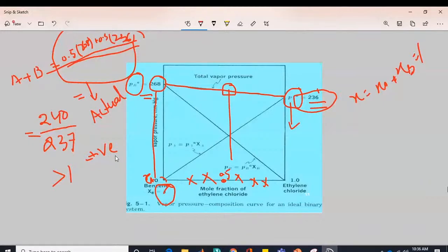Okay, the net result is an increase in the rate of mass transfer into vapor. Now this is another equation to understand how vacuum distillation works. Actually, it is the mass of the vapor formed, you can say. The equation is the vapor pressure of the evaporating liquid divided by the external pressure. Now remember, we are talking about the mass of that component, how much can be achieved. We have two factors. One is the vapor pressure of the liquid which is getting evaporated, and the other is the external pressure. What we are doing is dividing the vapor pressure of that liquid by the external pressure.